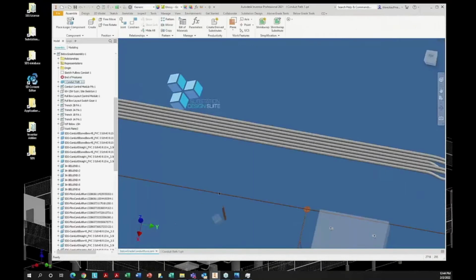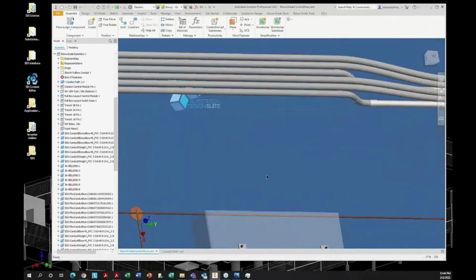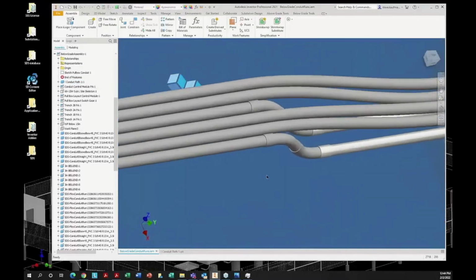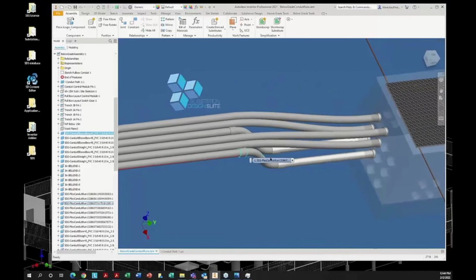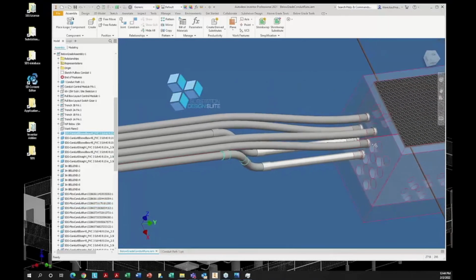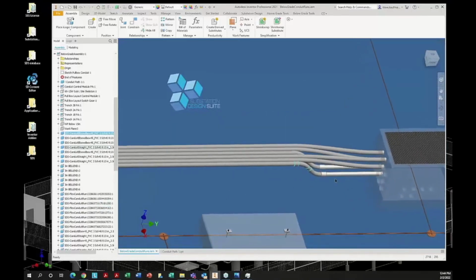And that's what I'm using to place my conduit. So when I place my cylindrical conduit, I pick those cylindrical edges from where I want to start. Well, I want to start on this flex conduit from my elbow, right? So I'm going to start this one from the elbow. Because this one's going to be bent or pushed, heated, whatever it's done, I'm going to start it from the pull box itself. I'm going to bring it out. So that's the method I'm using here.